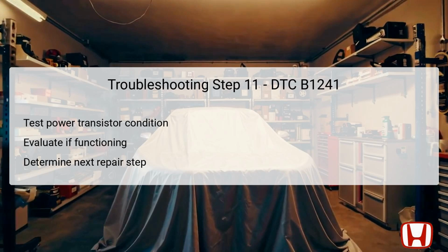On the other hand, if the power transistor fails to meet quality standards, you must replace it. Importantly, after dealing with the power transistor, always verify the blower motor for any signs of damage and replacement requirements to prevent future malfunctions in the wiring system.